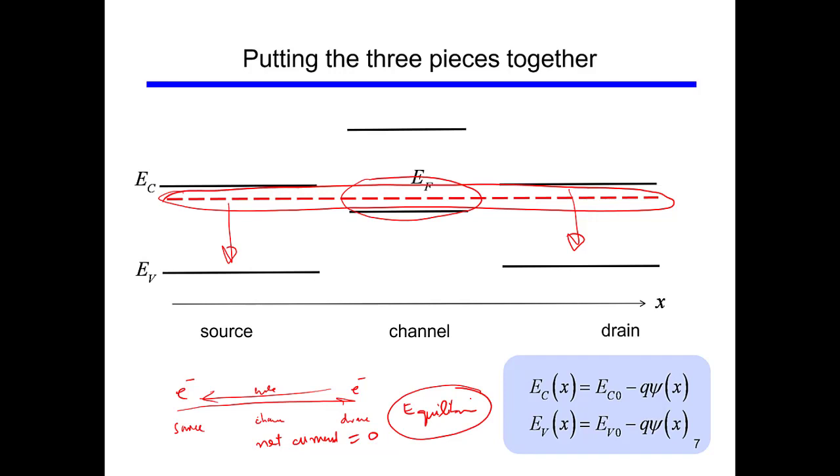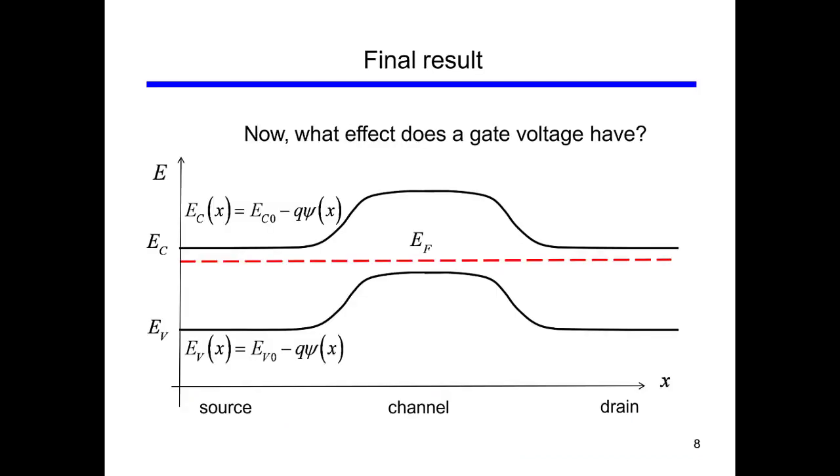So in order to align all three Fermi levels, the Fermi levels of source and drain have dropped, and that's why the conduction and the valence band of the channel have moved up. Okay, so this is another picture that shows the same.